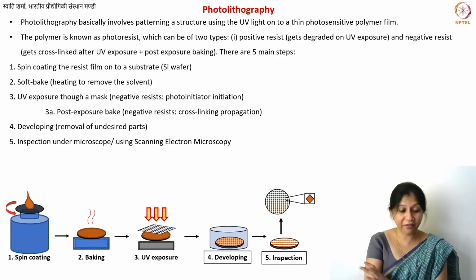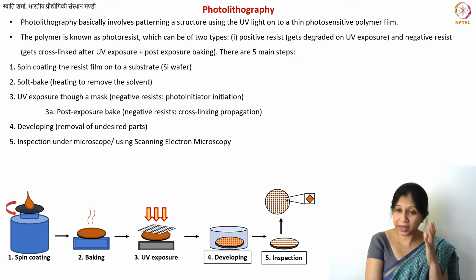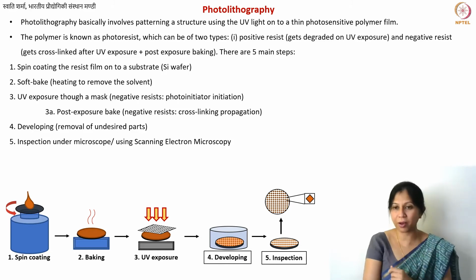Now, having said that, there are other polymers that have also been tried out for whether or not they yield glass-like carbon. There are several papers you can read. The point is that the material should undergo coking, and in the case of microfabrication, these are specialized polymer resists. Sometimes you don't know the exact chemical structure of a resist.